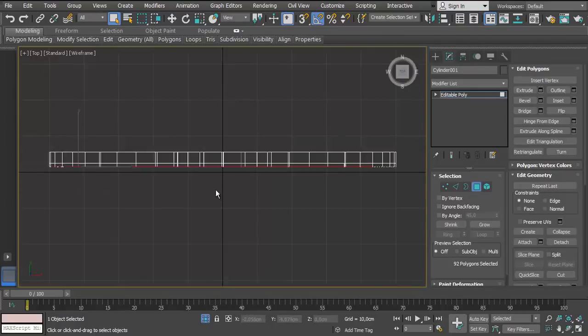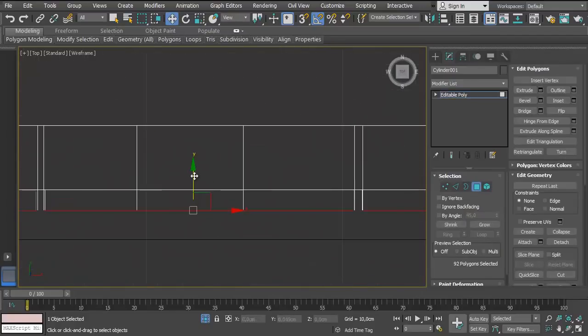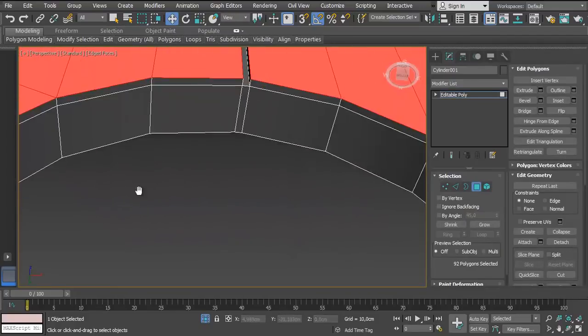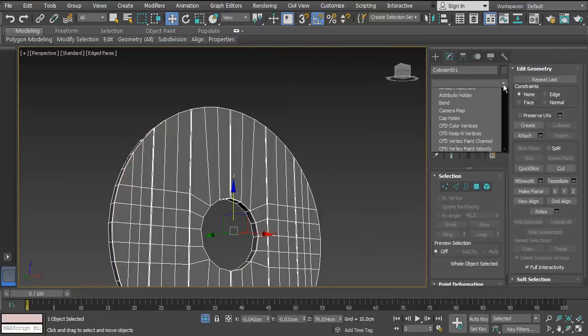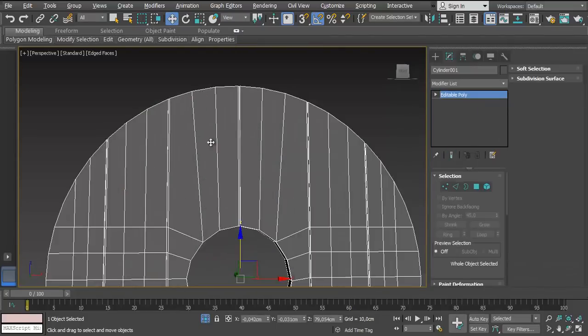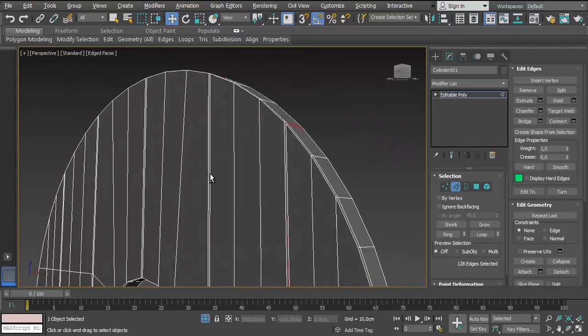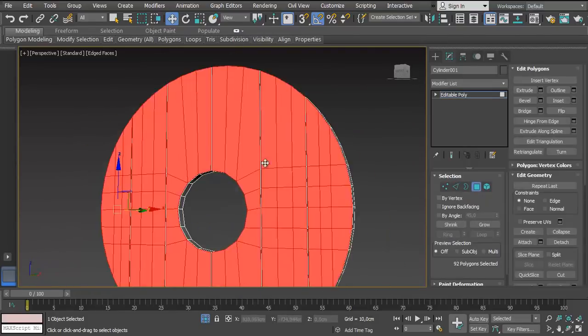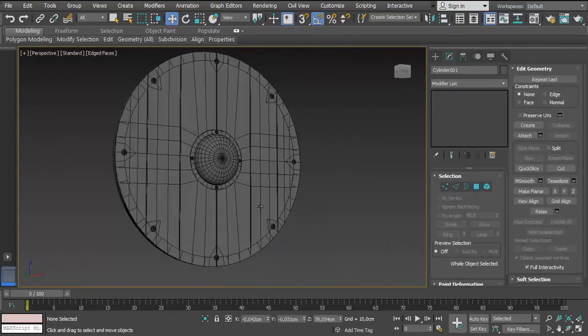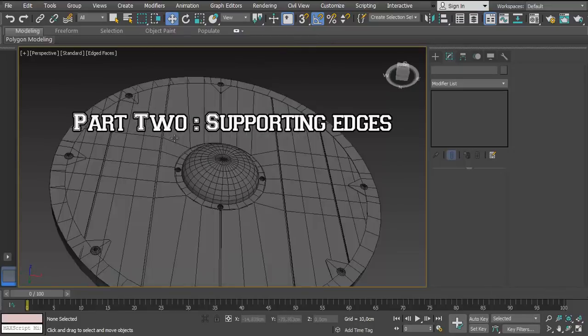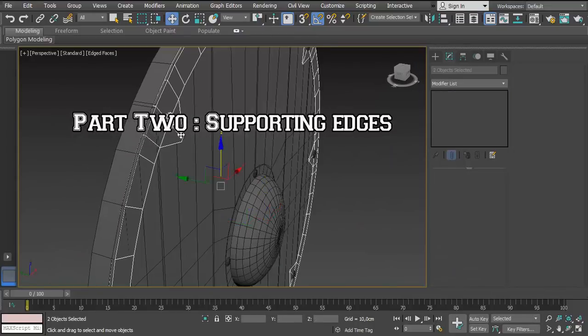What we are going to technically do is extrude the areas that extrude negatively, which means we extrude with a minus value, or we extrude with a positive value the areas that are not going to be carved. Both ways are going to work.